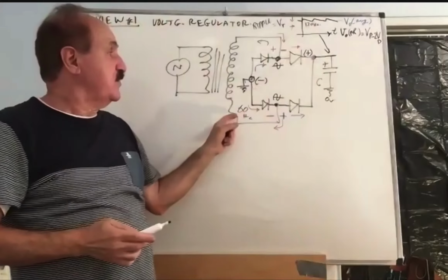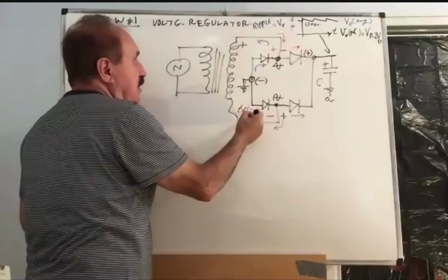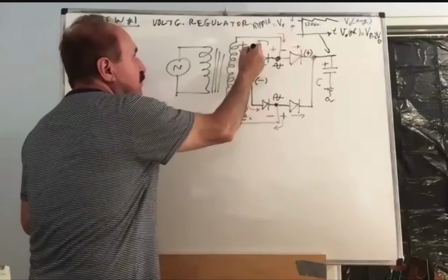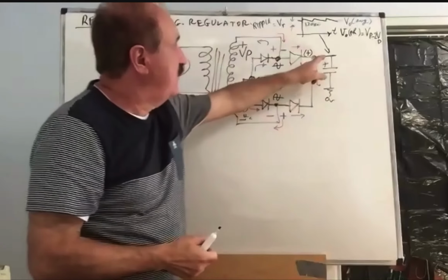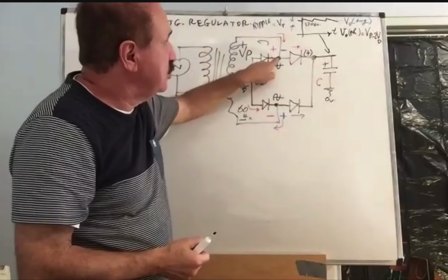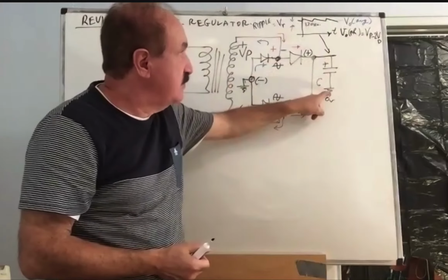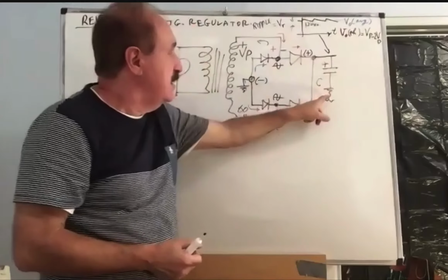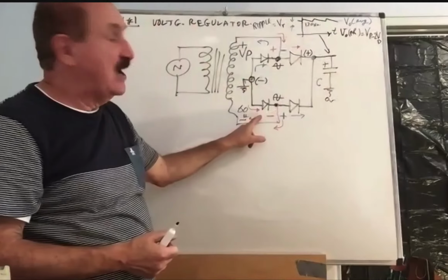The reason is, if you have a peak voltage across the secondary VP, if you write the Kirchhoff law, you will find that the voltage is up to VP, then it drops by 1 diode voltage, then you get the output, which is the output peak, and then it drops again when it is returning through the adjacent diode.